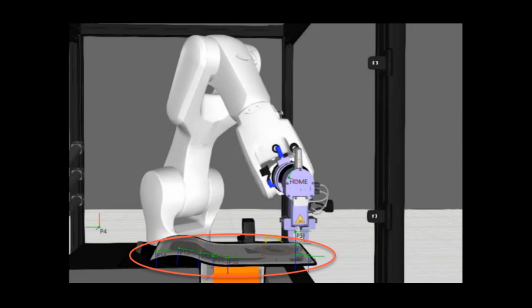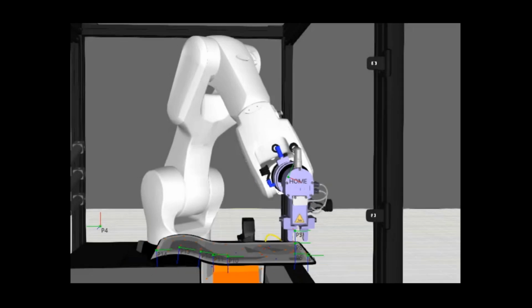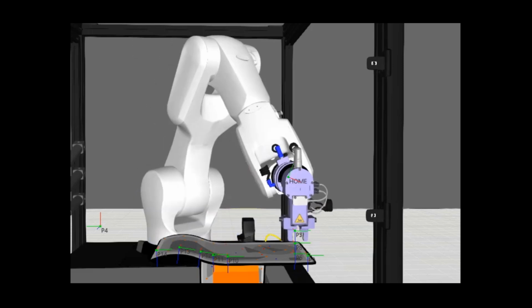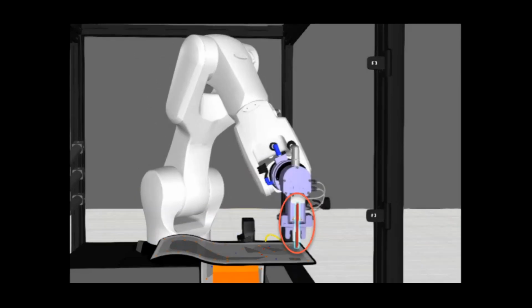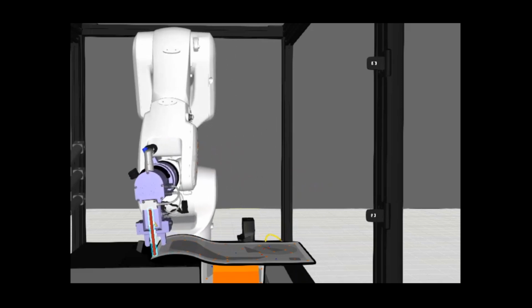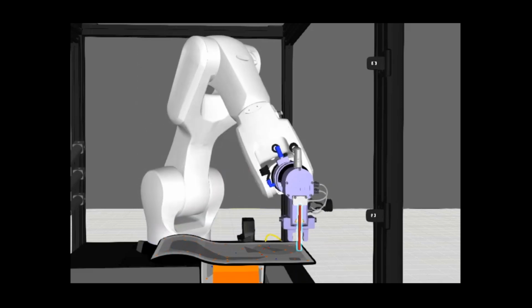So for example, if you wanted the robot to follow a surface, you normally would program a path with many points to follow the surface. But with RSI, you could set up a distance sensor behavior to follow the surface at a certain distance away. Then you could program a single point for the start and end of your path, and the RSI behavior would handle detecting the surface and automatically adjust the path to maintain a certain distance from the part, regardless of the shape of the surface.